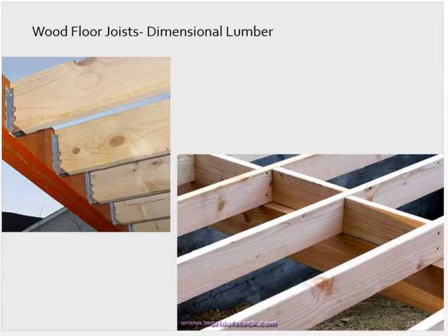Alright, moving on. So wood joists come in a number of varieties. So this is all dimensional 2x lumber. Here we see the joist running over the top of the girder, easy installation. And then we have the blocking over the girder to keep the joists rigid. Here we see the dimensional lumber flush with the top of the beam, and we see joist hangers wrapping around. So the joist hanger would be put on at the same time, and then the nailing could be finished afterwards.